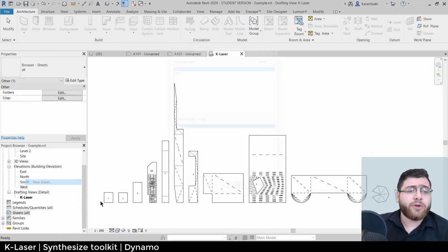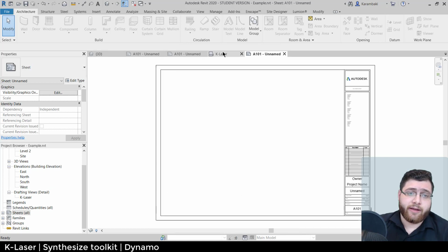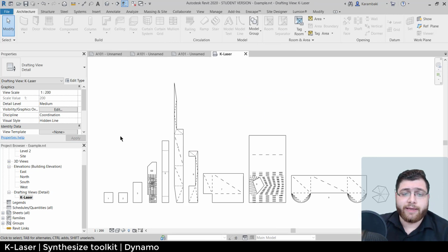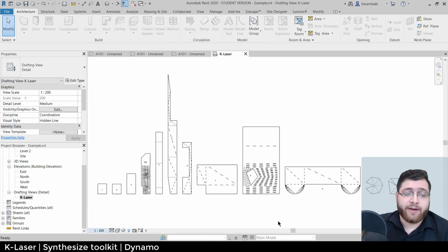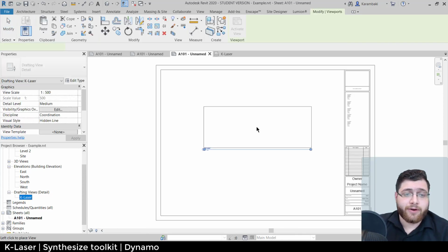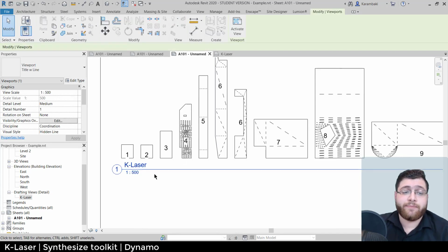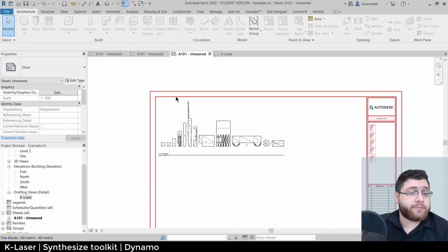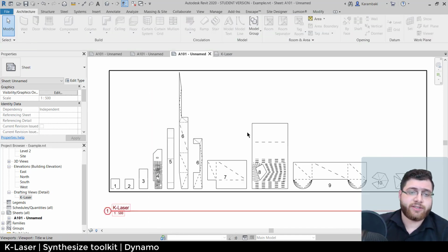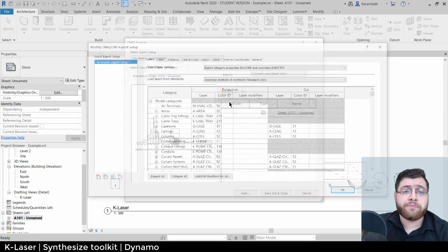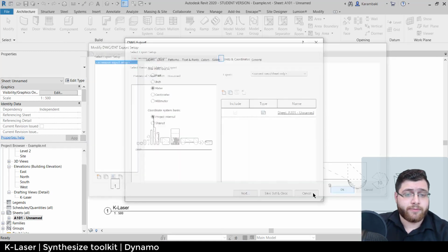It's always nice to choose your modeling scale. For example, if I want to model all my things physically at 1/500, I can simply put 1/500 here and drag it here, and I will have all the units and pieces at 1/500 scale. That's cool. Now let me just export it. Of course, you can delete the sheet itself. The important thing is that you are in a sheet view. Now export CAD DWG. Alright. Make it meters, and next.